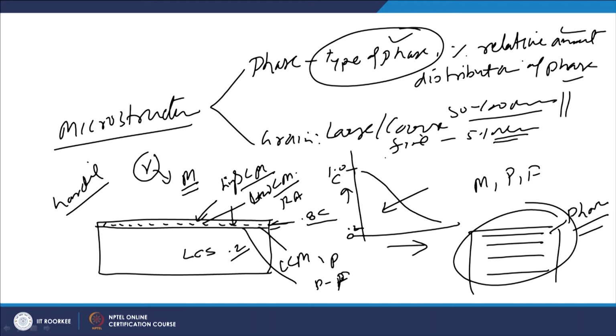Apart from that, what is the shape of grain? The spherical and equiaxed grains offer the better resistance to the wear as compared to the needle shape or sharp edged polyhedral shaped large size particles. So, the shape is characterized.